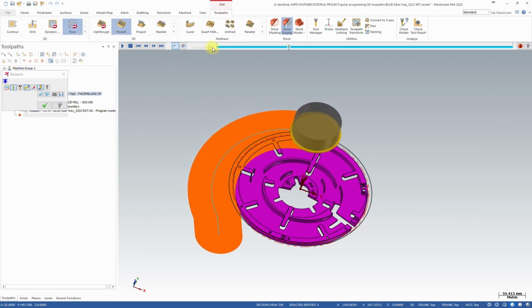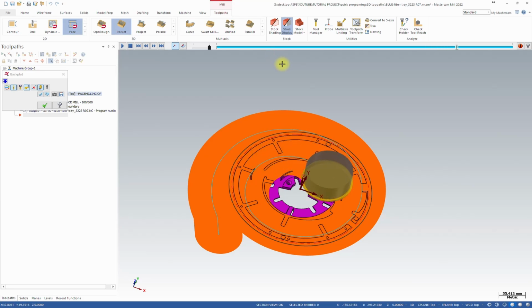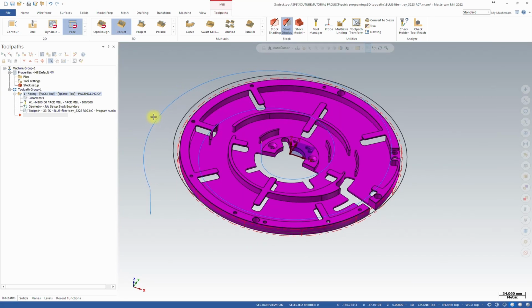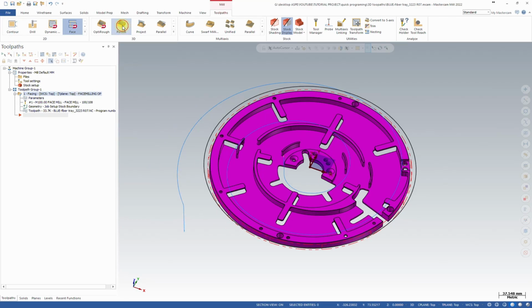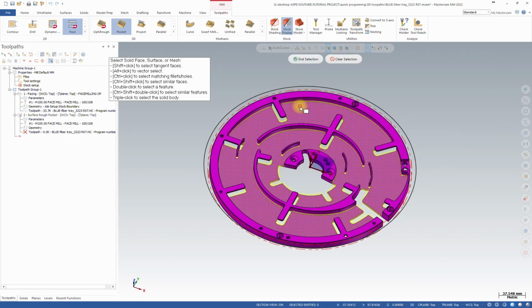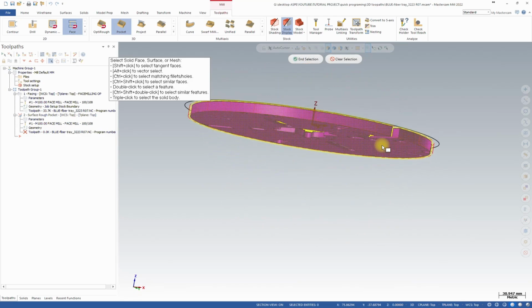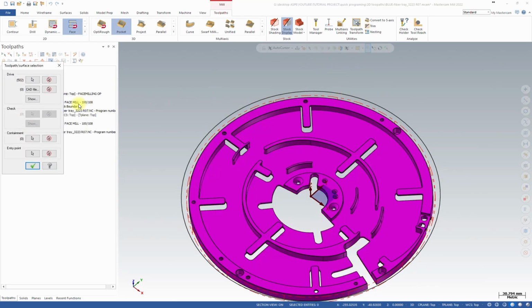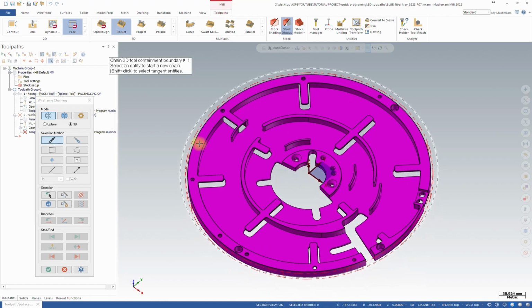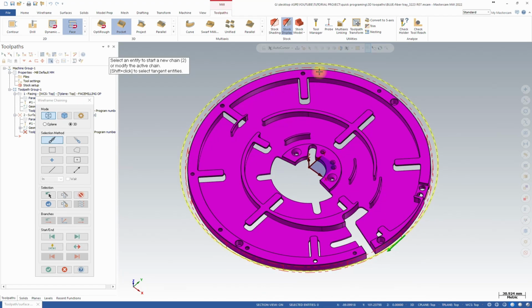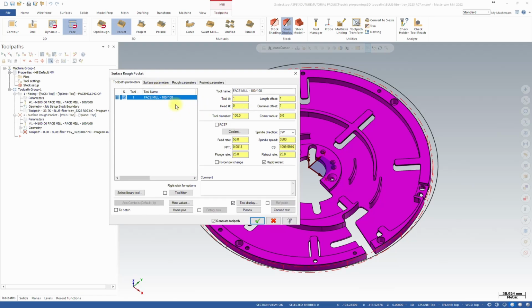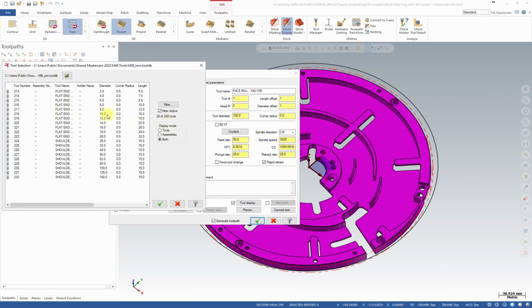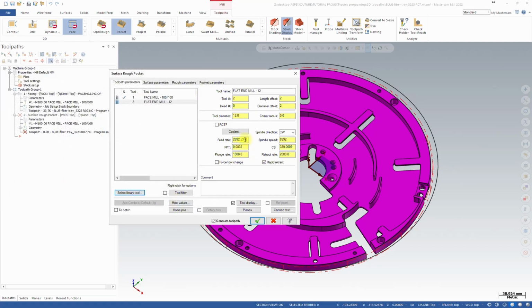So with our next toolpath, we're going to rough the part out, and this time instead of OptiRough, as we use that in many of our other tutorials, we're going to use 3D Pocket. And triple click, I selected the whole 3D model. Containment, I'm going to select this circle, this wireframe that I created. Okay. And as my tool, I'll use, let's say, 12mm flat end mill.